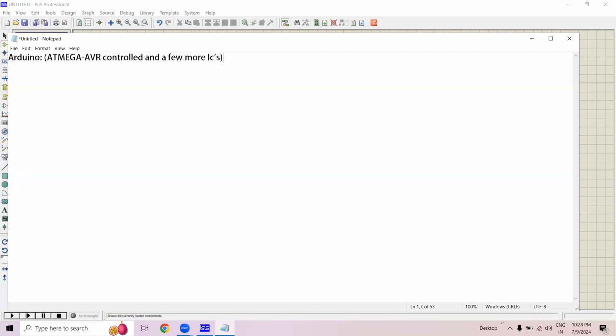Sometimes if we want to sleep and sensor is going to turn off the light when we go outside, we can use the manual switch to turn off the lights. Or otherwise, sometimes when the sensor is not working, we can control those lights manually. So wherever we apply automation, we have to put the option of manual as well.